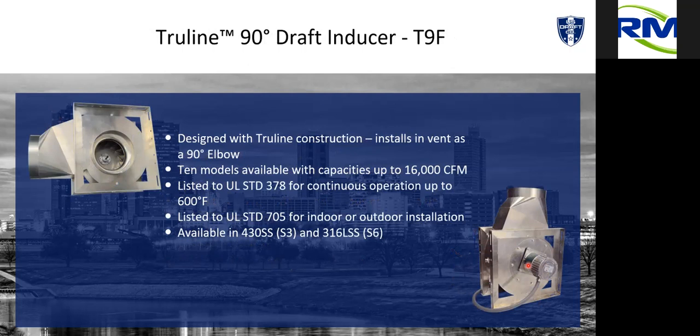Our T9F goes up to 16,000 CFM. The design is slightly different on the larger sizes, but it's basically the same concept of a 90-degree fan. Many people use this as their horizontal to vertical transition. Works really well for that. Again, we are not going to be the system drain. We do have drain plugs on all our inline products, but we cannot handle the amount of condensate that's going to be in the entire system. So we want to make sure that we have proper drainage per the venting manufacturer on our system.